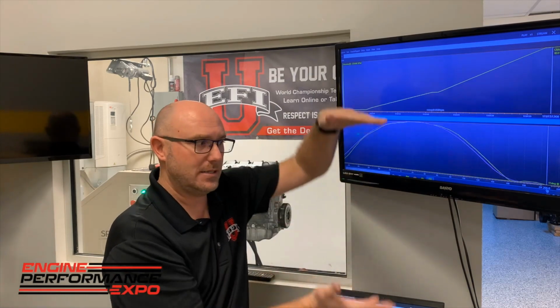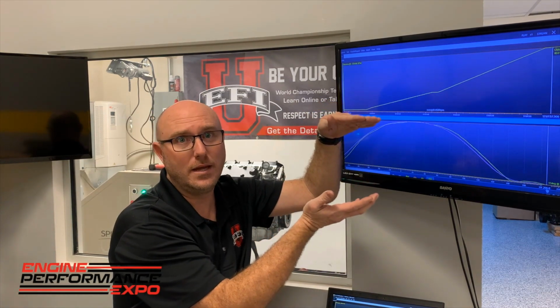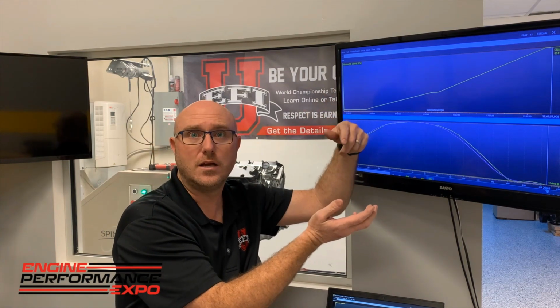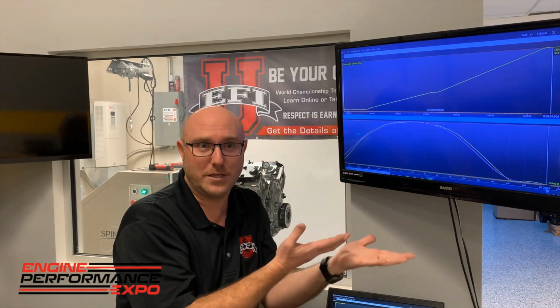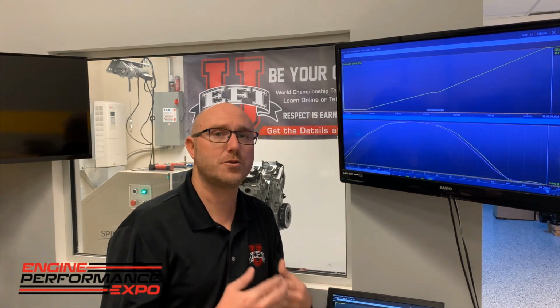Now keep in mind that the entire stroke for compression is only 180 degrees. Well, we just lost the first 100 of them. And now let's think about it. Typically, I'm going to fire my spark plug before top dead center, let's say 30 degrees. That means I really only had 50 degrees of total time to compress the mixture before I lit the spark plug. Well, you can understand why when that happens, the engine's performance drops off like crazy. So for obvious reasons, we want to try to avoid that.